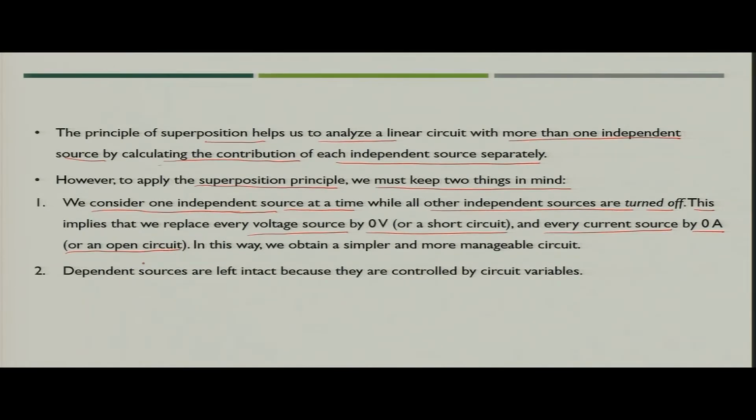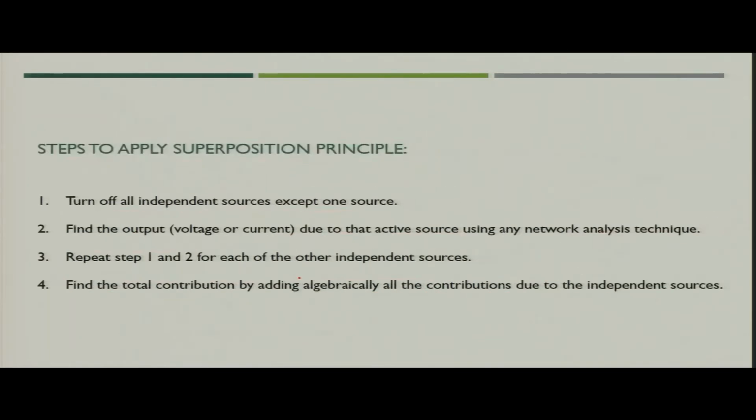Now, the second important thing is that you cannot apply that particular assumption in the case of dependent voltage or current sources. You have to keep them in the circuit and solve as you have solved other circuits, like using nodal analysis or mesh analysis. So, dependent sources, maybe voltage or current sources, should be left intact in the circuit.